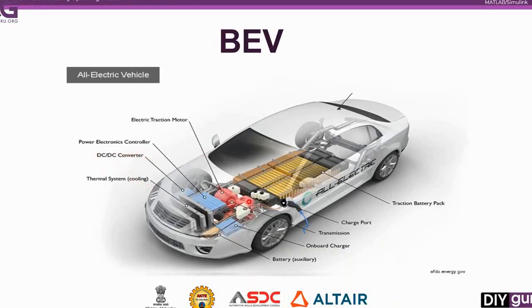Then we have the DC-DC converters. So what is this thing doing? Because we have a particular type of traction battery pack, depending on the required voltages, we will be using this one. But either we have to step it up a little bit or step it down a little bit for use by the traction motor. So we will be employing a DC-DC converter that will do the conversion for us. So either it will ramp up the voltage or it will lower the voltage.